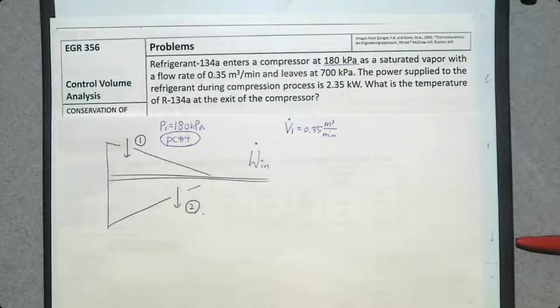No, that's why we want to use mass flow rate rather than volume flow rate. Because volume is not conserved. So if you use the volume flow rate, it is not the same as the volumetric flow rate at the exit. But if you convert this into mass flow rate, that mass flow rate is constant. Conservation of mass principle.